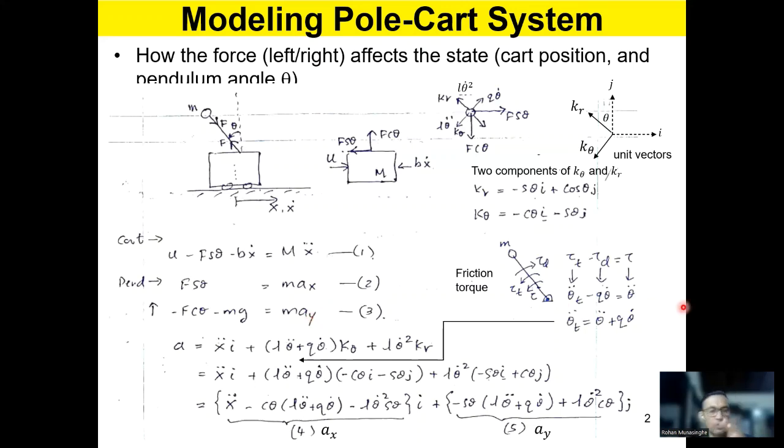Okay, so why I explain the entire thing today to you is to refresh your memory on modeling. When you are dealing with a relatively complex plant, this is the type of approach. You have to draw the system and get the free body diagrams, then assign the vectors and look at the energy balance, and then write down the basic equations of motion, right, like that. I hope this will help you revise your basics in modeling.